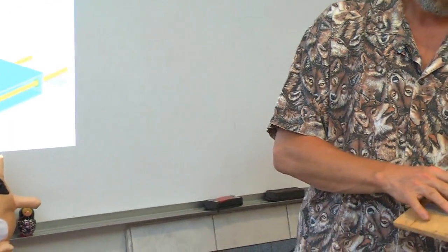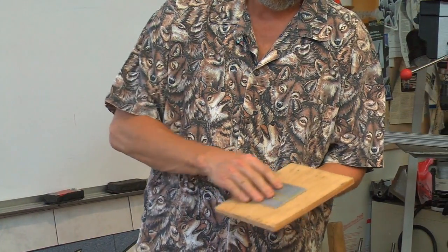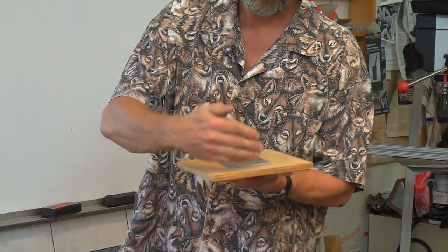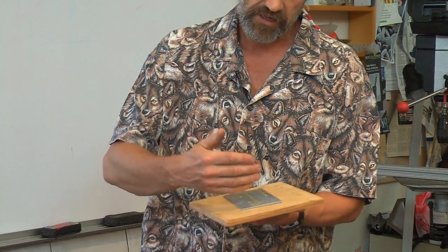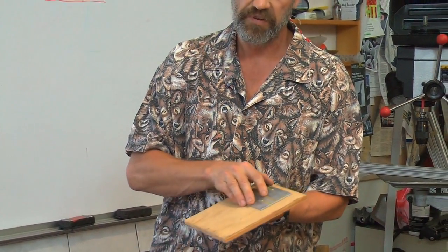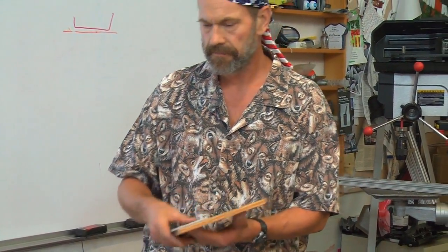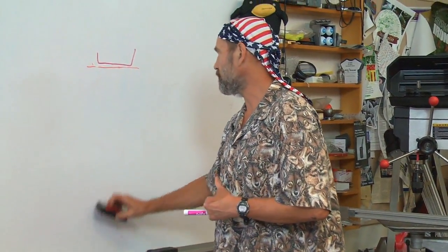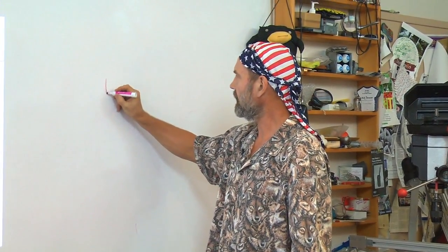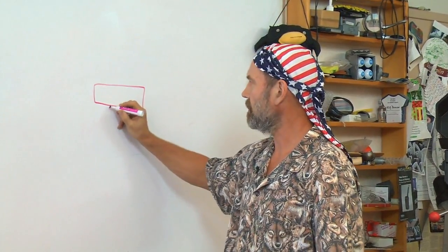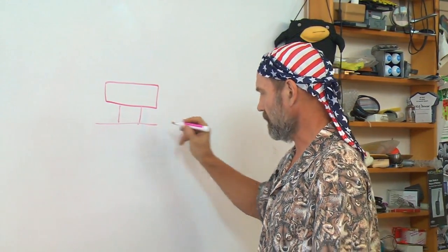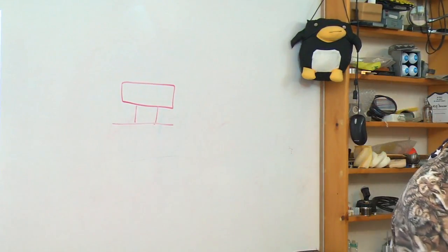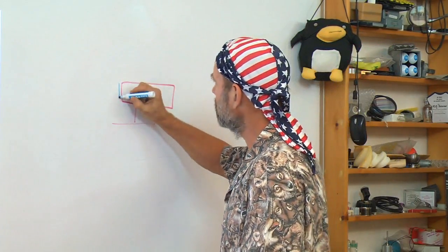But that flat on flat has only stiffness vertically. You have to put other features, and hence other sliding contact bearing surfaces, to provide the guided motion you want. There are many different geometries with which to do that. I can have a bearing rail, and this is called a boxway structure, with bearing pads.